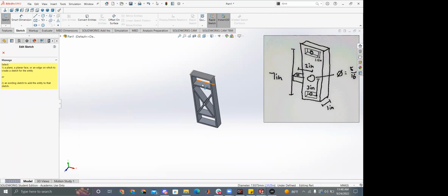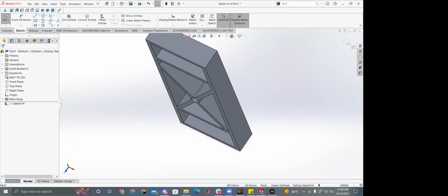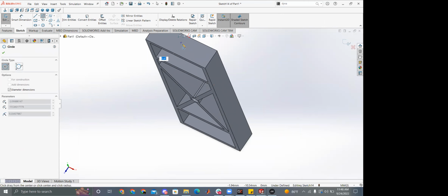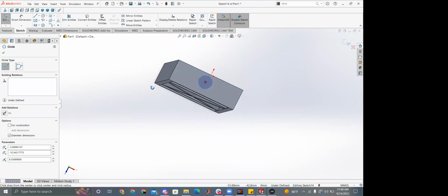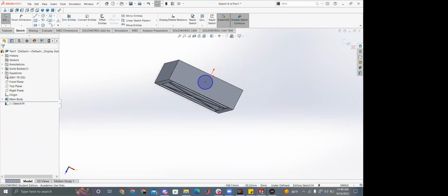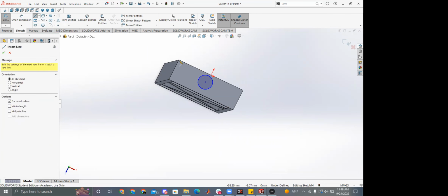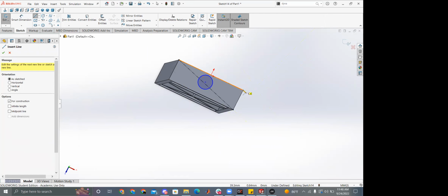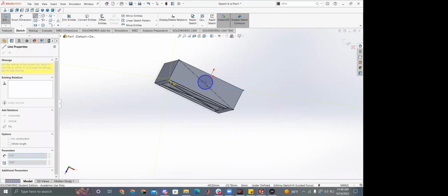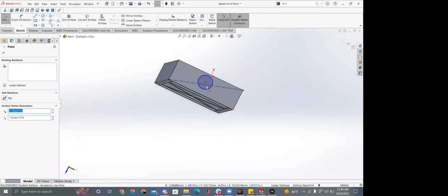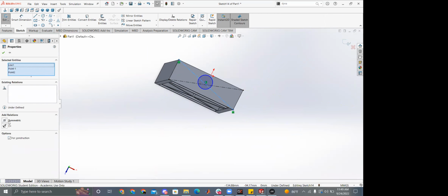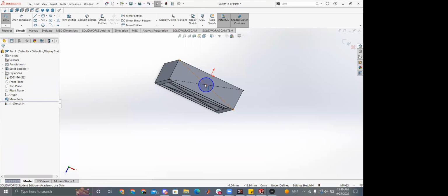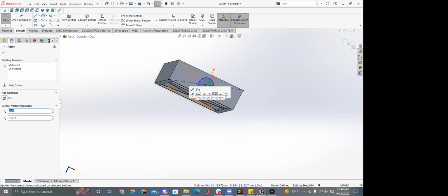Sketch from the top. We want to put this hole in the center of the face. Something we can do is define 2 construction lines crossing the center. They meet at the center because geometry. So we can set those, why does it keep looking to line? Put those to be coincident with the center of the circle, and it will snap the circle to the center, and notice the circle can't move from that center point anymore.